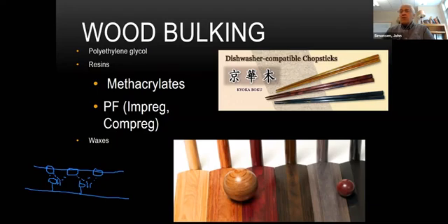So another place where they're used is bow and arrow. If the bow is made out of wood and the arrow is made out of wood, probably it's got some kind of a treatment. And pool cues, where you shoot billiards, those typically also have some kind of a treatment to give them dimensional stability. All right. And of course, waxes. Typically you want to prevent moisture, you wax something up. So you can inject wood with waxes. And so you basically have a very high water repellency.